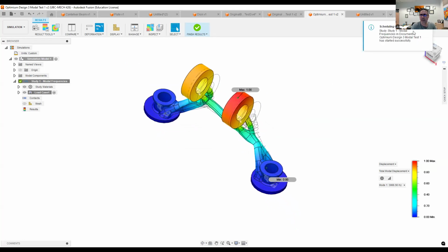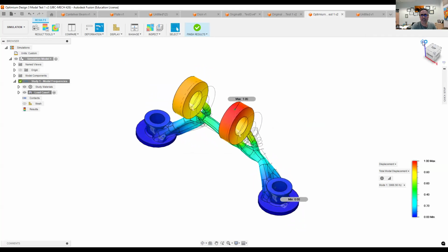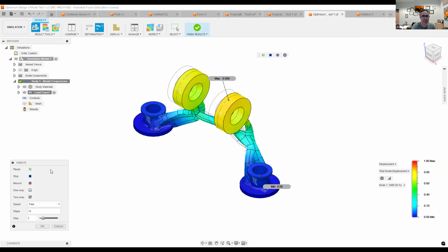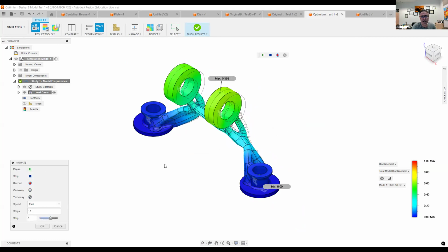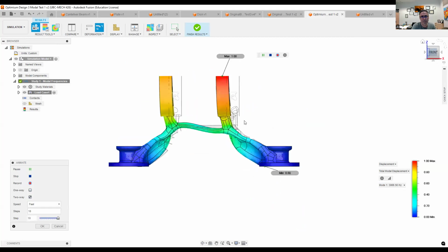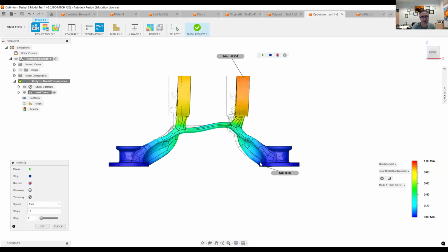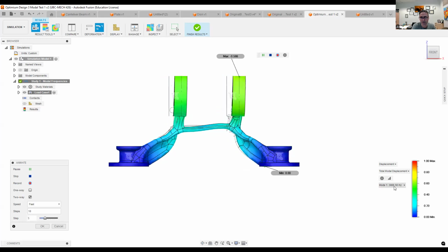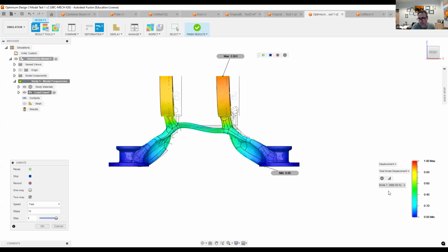Well, here is our bracket, perspective view, the first frequency is 3606, and then let's look at the motion. It's very, very similar to what we saw for the other one, but now it's of course a bit different, with more motion on the base as well. And the frequency is about 3000 hertz.